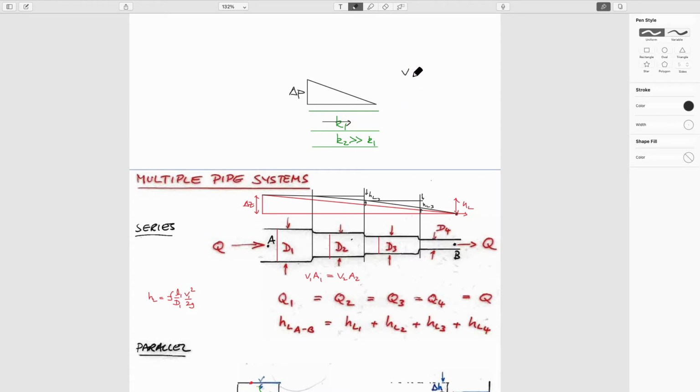So you'd expect some flow to go through this stratum driven by this flow. You remember Darcy's law. Velocity is equal to permeability over viscosity times the pressure gradient. You'll see this in your other classes often. This is permeability. So in this particular arrangement, the flow will go a little bit down here, but a ton of flow will go here because the velocity will be very high, as this will be a large number. And so preferentially, if you look at the flow coming out into a bucket on the other side, there'd be a ton of flow coming out of one bed and not much on the other. To calculate the flow across this system, if you're trying to get fluids out of your reservoir, either for water supply or for hydrocarbons, most of the flow would occur in this bed.